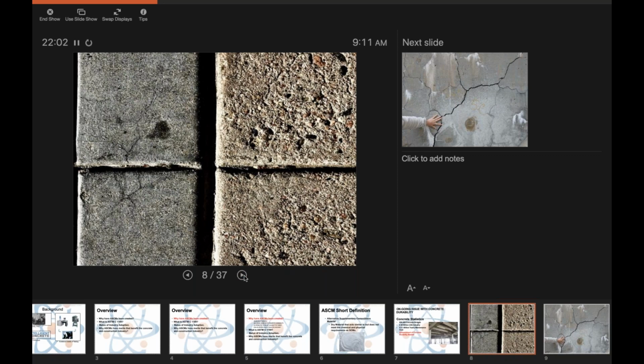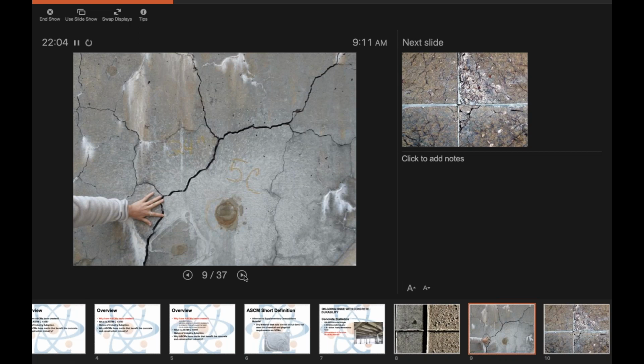Next slide, please. This is something that we haven't talked about, this durability problem. Oftentimes when I bring it up at ACI, ASTM, I get people who roll their eyes at me. Normally they're from Chicago or New Jersey or Pennsylvania, where they're still burning coal. They say, John, we don't have a problem. Of course you don't have a problem. I'm not talking about you guys. I'm talking about the folks out here who do not see the Class F fly ash, where they need 20 to 35%.